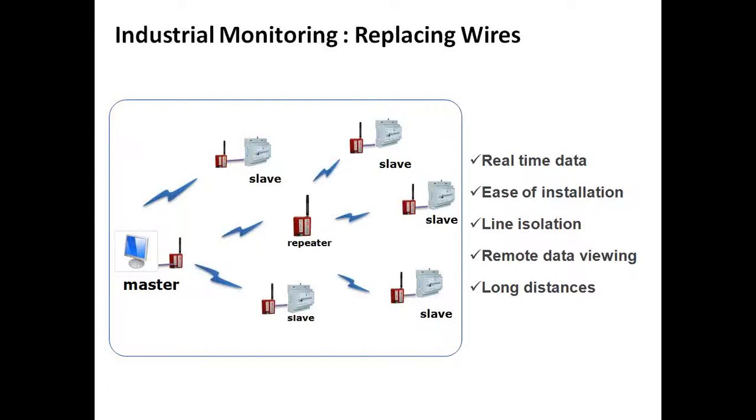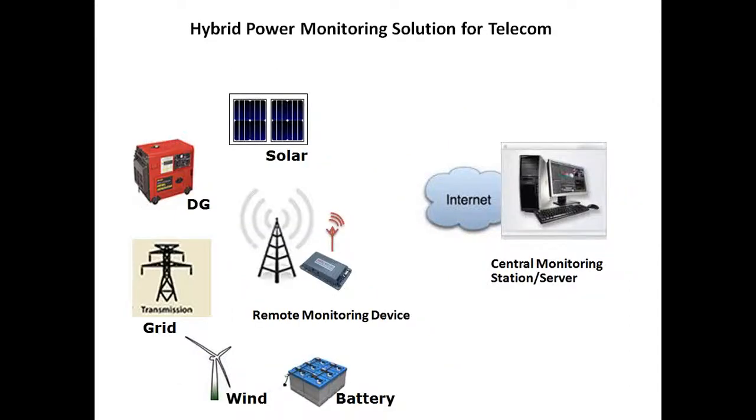Okay, another one is industrial monitoring. On the industry floor, a recent trend has been to deploy wireless monitoring of process control systems. Some of you may know that a lot of industries are occupied with the Modbus protocol over RS-485 slave that may be running. Some of them may be running HART interface, and some of them may be running Ethernet interfaces in your factory floor. What essentially M2M can do in certain cases is to be able to deploy these wireless technologies connecting to the slave devices, and your master device is maybe your computer or your computer station that is monitoring all the devices. In this case, typically Zigbee is a favorite technology for using this.